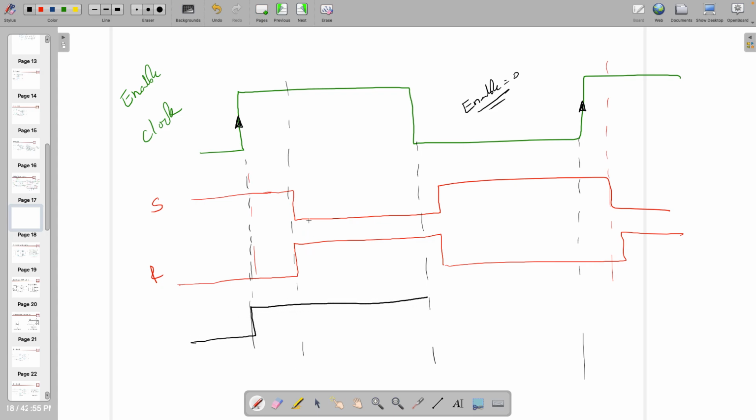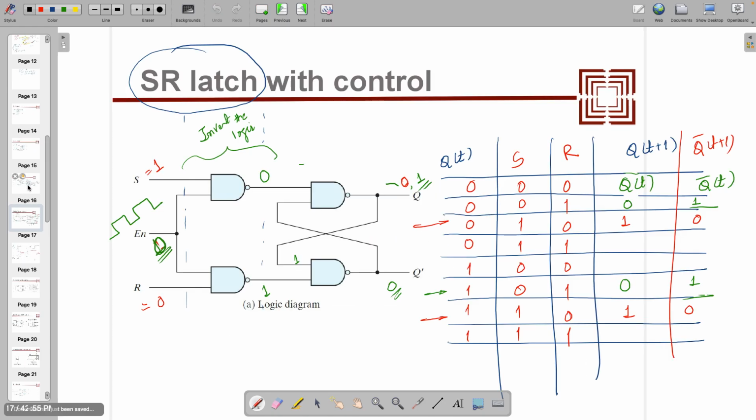In between, whatever is changing doesn't matter. Right? In between, whatever is happening, it's not going to change. We are going to study that, but this was just to explain how the flip-flop will look like. Flip-flop gives the output when it's transition from either 1 to 0 or maybe 0 to 1. Right? And for the latch, what we studied, it's level sensitive. You need 1 to get maintained throughout the operation. Right? So this is what. Any doubt in this one?